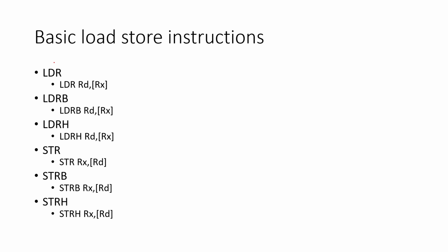So ARM-based microcontrollers basically use load-store architecture. That is, you can either load from the memory cell or store into the memory cell. So what does this mean is, whatever the data present in the address of Rx, for example, if I have something like 0x20000000, this is the address. Here I have a number called 21. If I want to take this into my register 1, what I'll do is LDR R1 comma R2. Before this, what I'll do, MOV R2 comma, or simply MOV, instead of MOV, let us use LDR only.